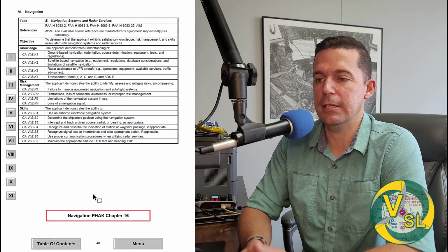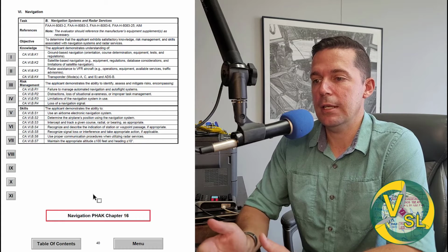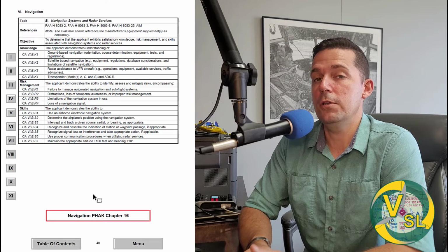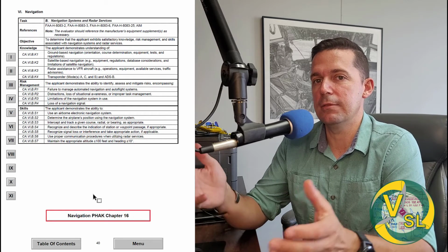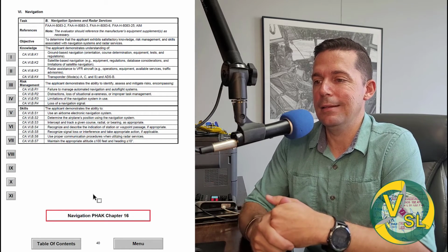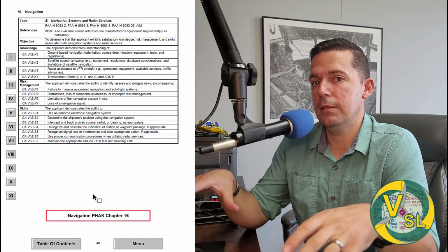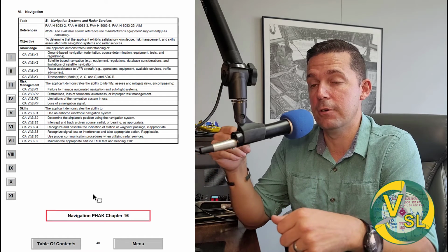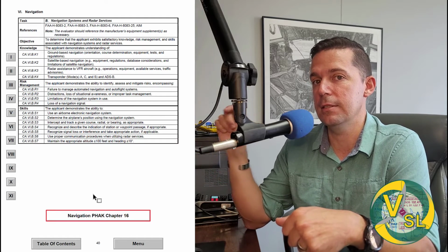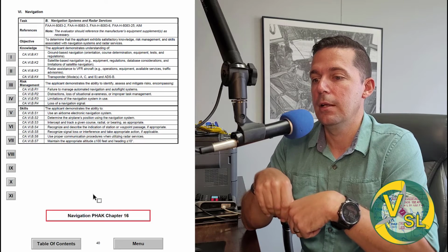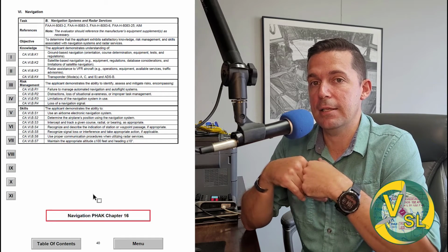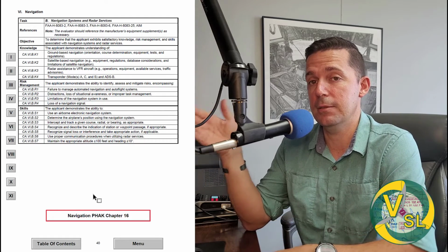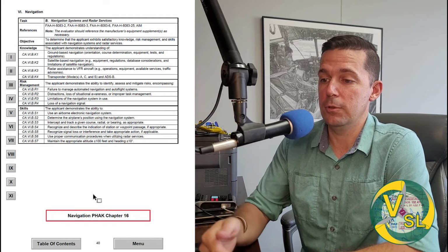They may explain a condition saying that you look ahead and you see a really big thunderstorm that appears to be over your destination. It's summertime. It's developed pretty rapidly. And it's kind of this widespread event that you can see out front. You're VMC right now, but you're definitely going to need to divert. And ATC tells you that this airport over here is the one you need to go to. So that may be the time that I ask you to, well, you can use all your available resources. So plug that into your GPS and give me an ETA, estimated fuel burn.